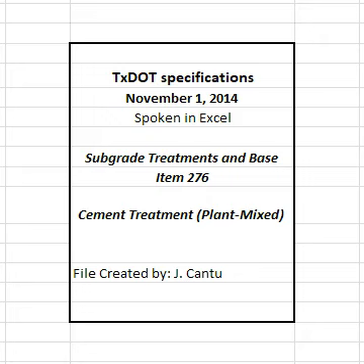Measure the moisture content of the material in accordance with TEX 115E or TEX 103E during compaction daily and report the results the same day, unless otherwise shown on the plans or directed. Maintain uniform moisture content by sprinkling the treated material in accordance with Item 204, Sprinkling. Begin rolling longitudinally at the sides and proceed towards the center, overlapping on successive trips by at least 1/2 the width of the roller unit.